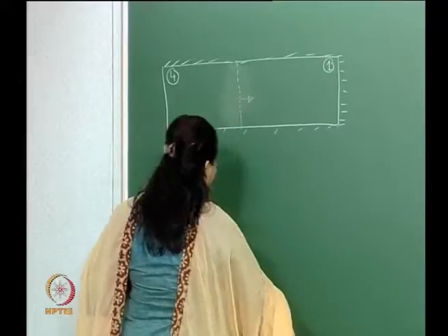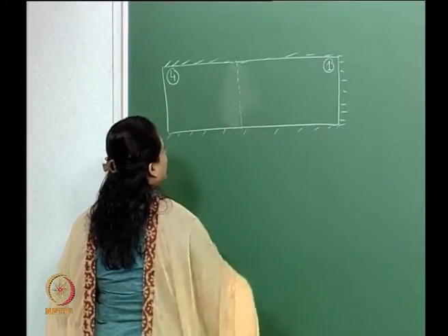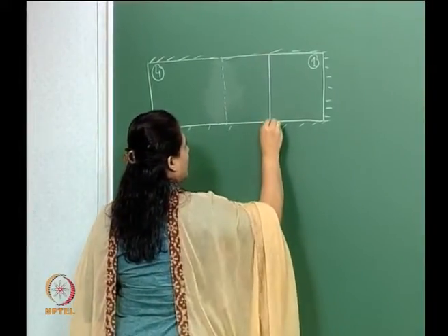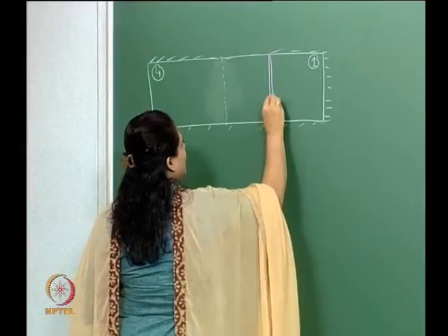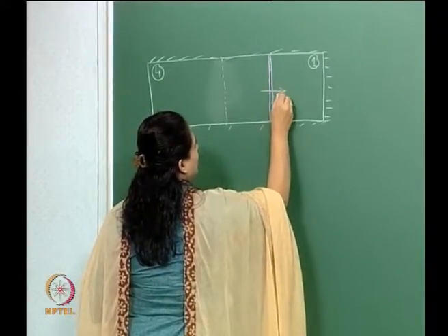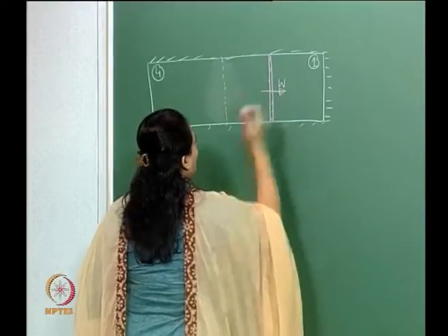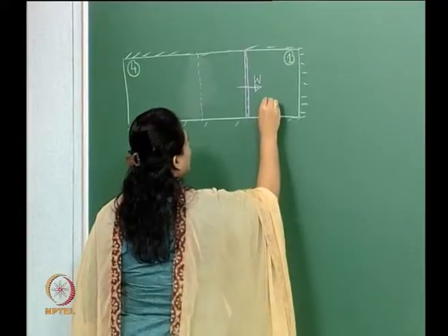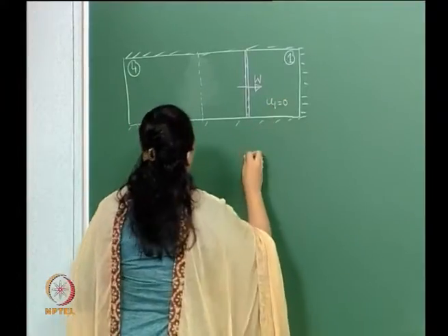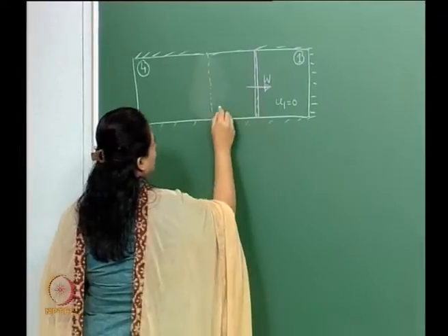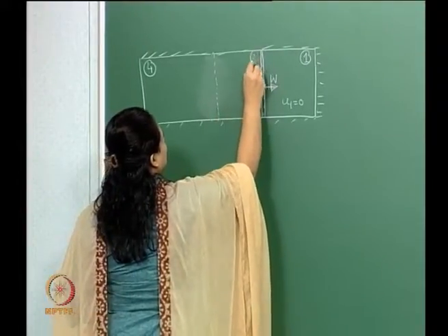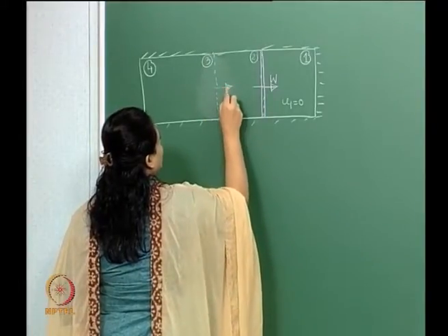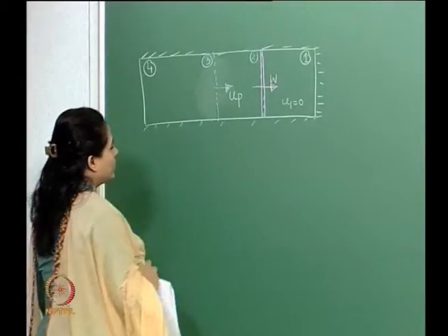So what we essentially have when we break the diaphragm is a normal shock, which starts moving into quiescent flow, and this induces mass motion in this region. We're going to call this region 2. We have the contact surface also, so this causes mass motion.